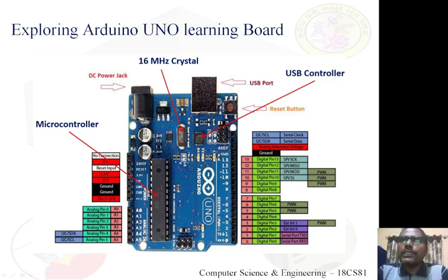Also, you can see some serial peripheral interface pins. For example, pins 13, 12, the SPI pins, also 11, 10. Now observe digital pins 0, 1. These pins can be used for serial communication. Digital pin 1 acts as transmitter, and digital pin 0 acts as receiver. So now we have seen 14 digital pins, 6 PWM output pins, some SPI pins, and the serial transmission pin TX and receiver pin RX.